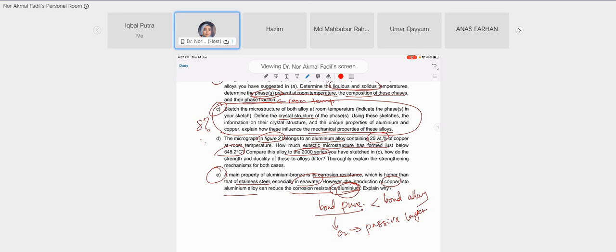It's not like stainless steel. Stainless steel has chromium, yes, but the base material is still what we call Fe. In seawater, stainless steel is not resistant to one very naughty form of corrosion, which we call pitting.